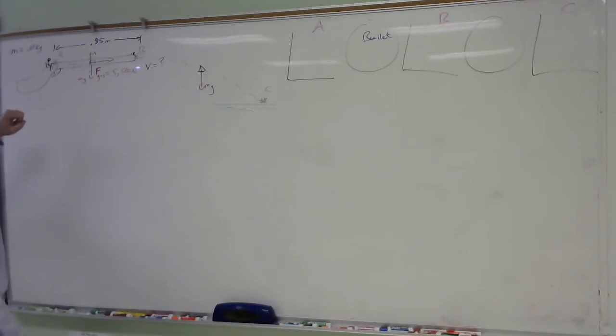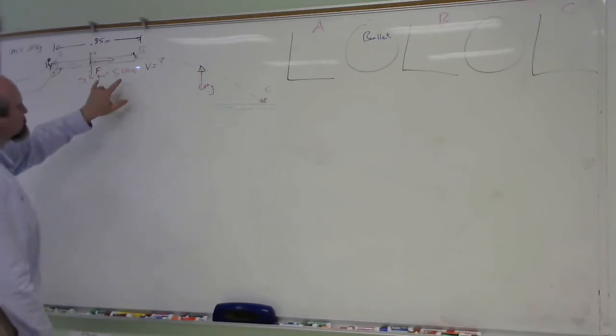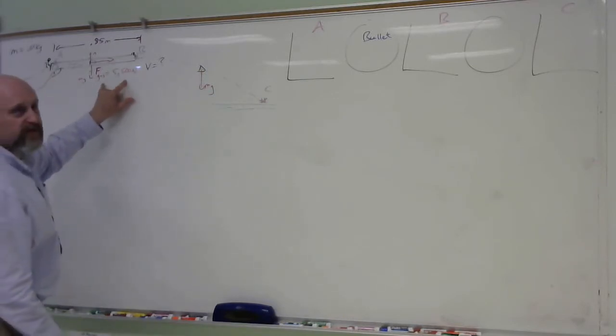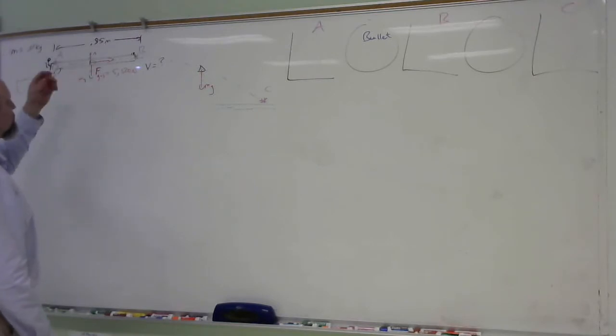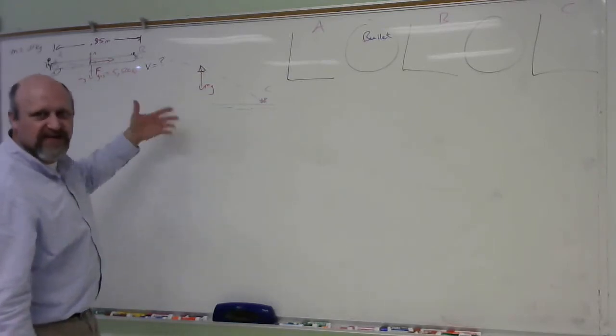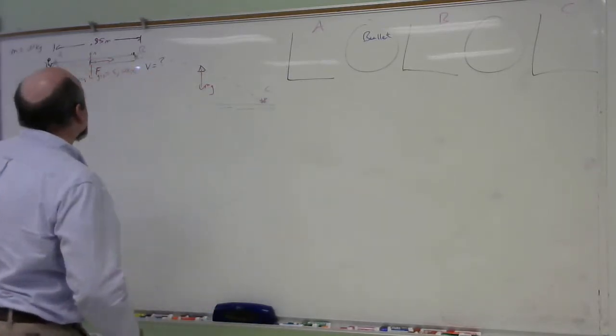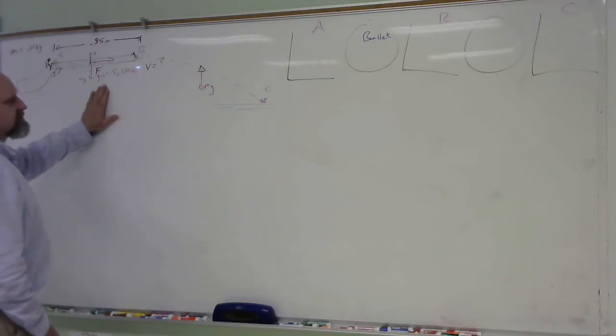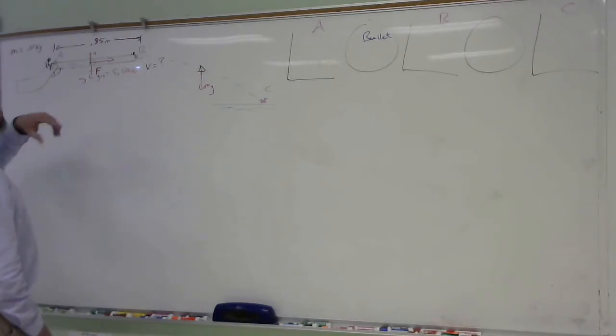Do we want to include the gases? No, because we're going to do a work calculation with this force. So we're not going to include it. We're going to make that a force from outside the system. They've given us that force. We're going to use that. So I don't want to include the gas in the system because we're going to have a work term.